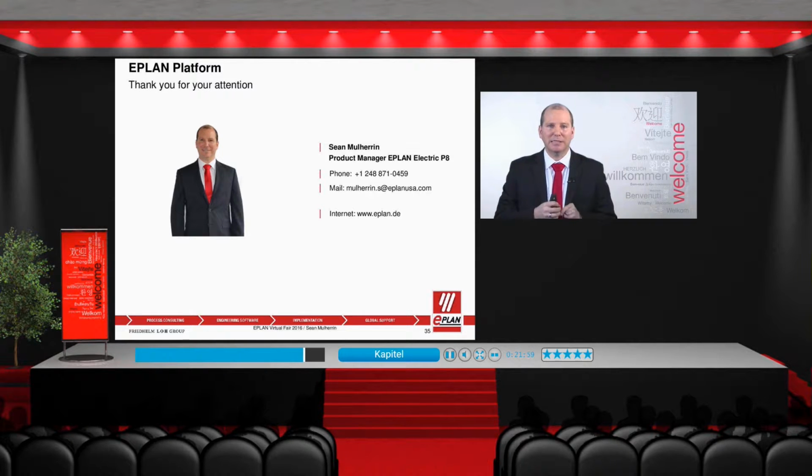The next question is: is the EPLAN platform compatible with AutoCAD? The answer to that is yes. We are capable in the EPLAN platform to import DXF DWG files, and we can also produce DXF DWG files. But as you probably know as well, the data in the AutoCAD drawings is very limited. You have graphical information and you have blocks with attributes, so a very limited amount of information. So when you bring that information in, it's mostly graphical data that you are bringing in.